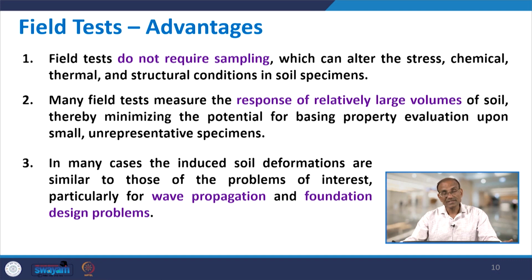As a result, when you take a sample from the field and test it in the laboratory, the sample you collect may not represent the real scenario. But in the field we are testing a large ground, so that will be more representative. In many cases of field tests, the induced soil deformations are quite similar to those of the problems of interest, which are expected during wave propagation and foundation design problems. So, in the field the conditions are similar to what is expected during the loading.